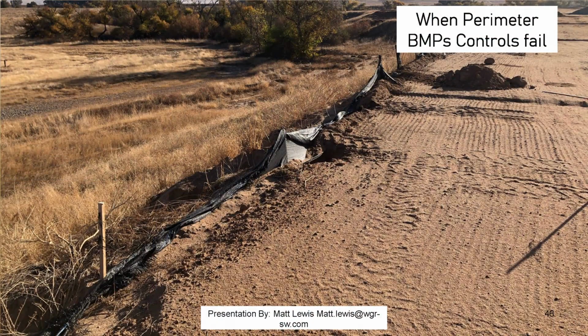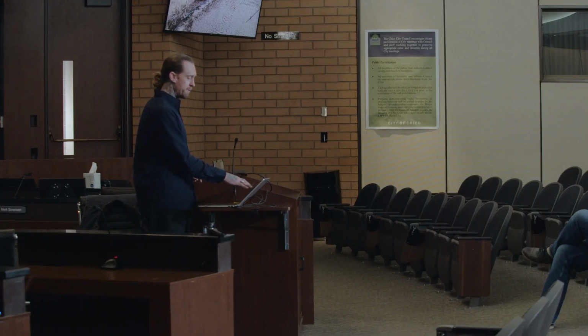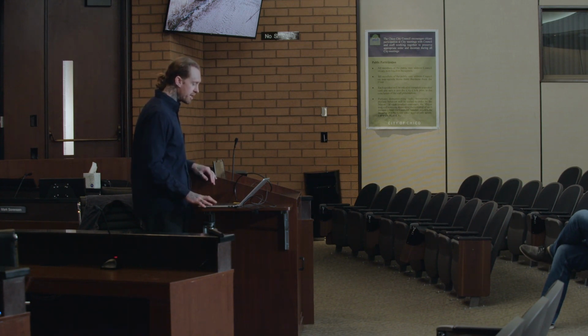And a lot of times, this silt fence wasn't keyed in. And as you can see, it's a little hard to tell, but the big dark spots are actually erosion that started forming and working its way under the silt fence. So if they're not keyed in, now this is not always going to work. You can sometimes install this stuff correctly, and water is a serious force to be reckoned with. But this silt fence was not keyed in properly, and it's led to massive amounts of erosion and huge time and cost loss.